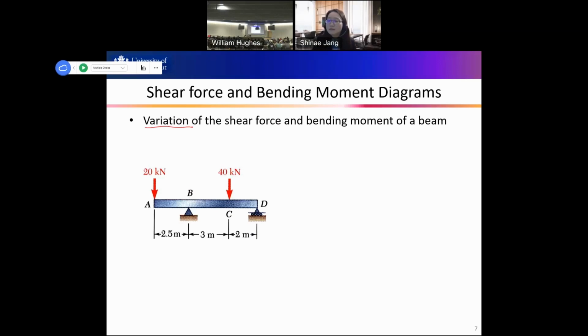distance, right? So if we have this beam here, and there are two forces, then we can cut here and then solve three equilibrium equations, right? So if we cut here, then we'll use the left side structure. On the left side structure, we only have 20 kilonewtons, so 20 kilonewtons is added. And then at the cut section, we add unknown internal forces. Technically, we should add three: N1, V1, and M1, and then solve three equilibrium equations, right?